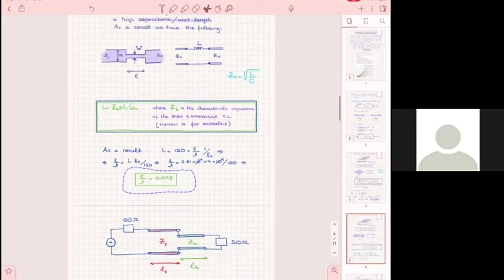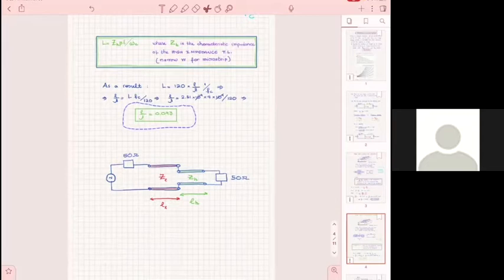You will see in some books that when we call it stepped impedance, stepping in the characteristic impedance, usually that's how we show it in an ideal transmission line form: a high impedance, the green, a low impedance, the red. So this is the high impedance section, and this is the low impedance section. And we have found the two lengths. So that's how you do this filter.